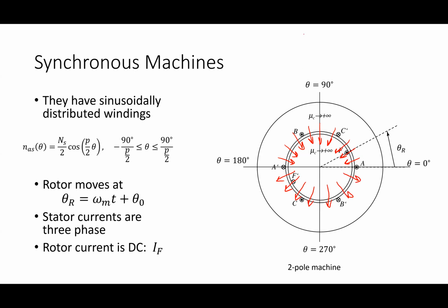So if I plotted that as I went around, from 0 to 360 degrees, with 0 degrees over there and 180 on the other side, then in this case, if I do B_A of theta like this, I'm just going to assume that I have a DC current in that winding. Which direction does the field go from 0 to 180? Yeah, it goes inward radially.